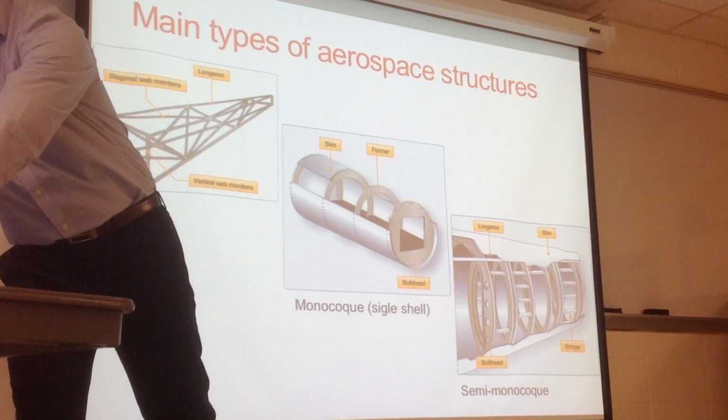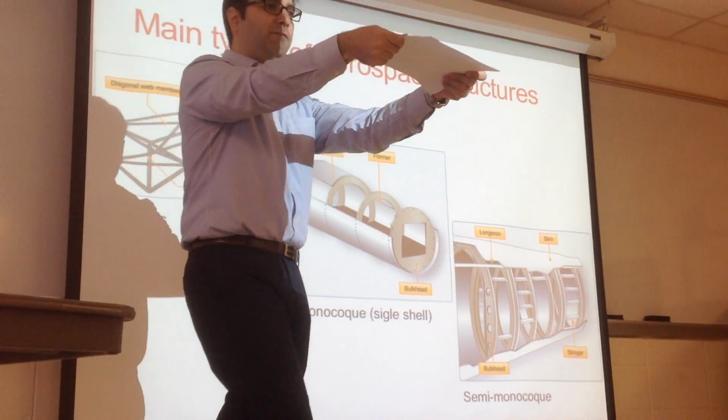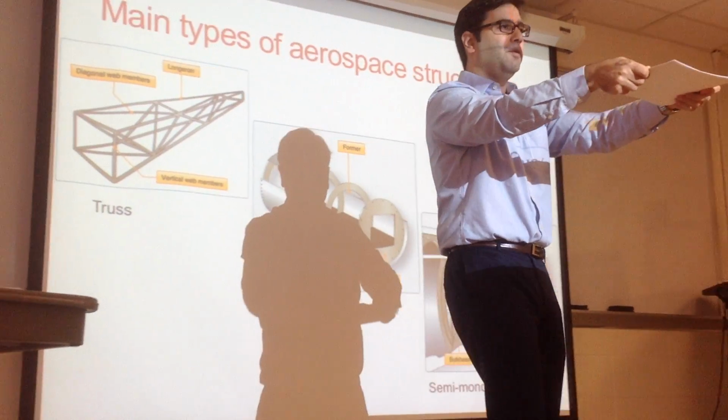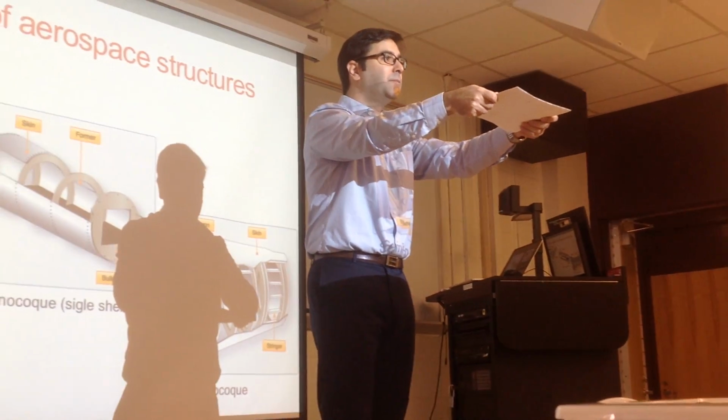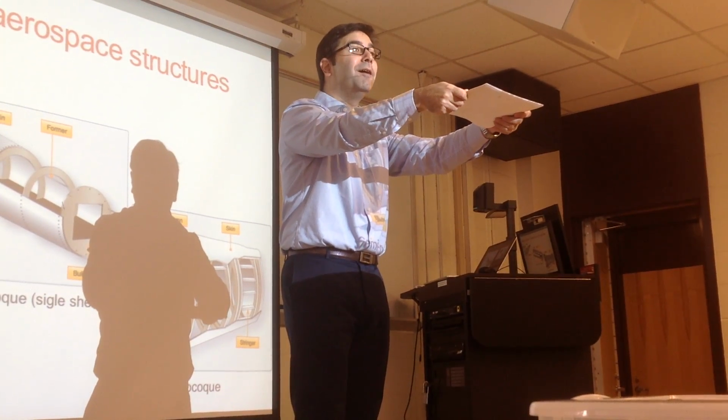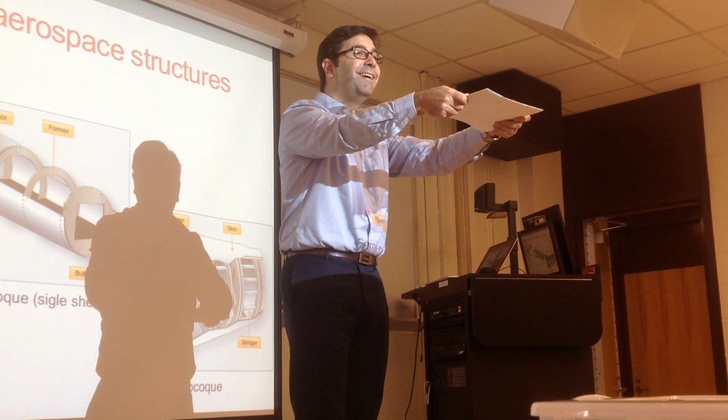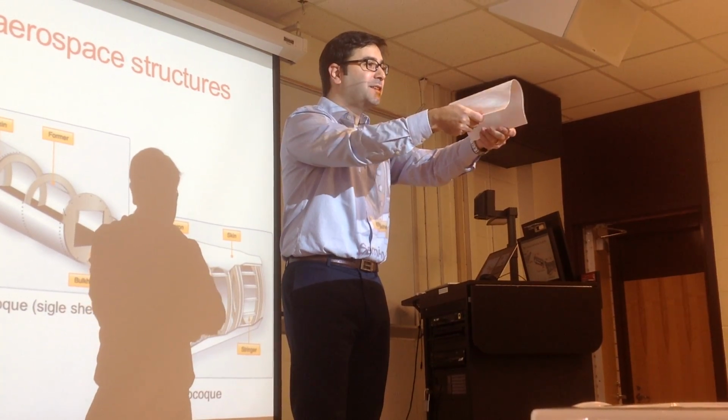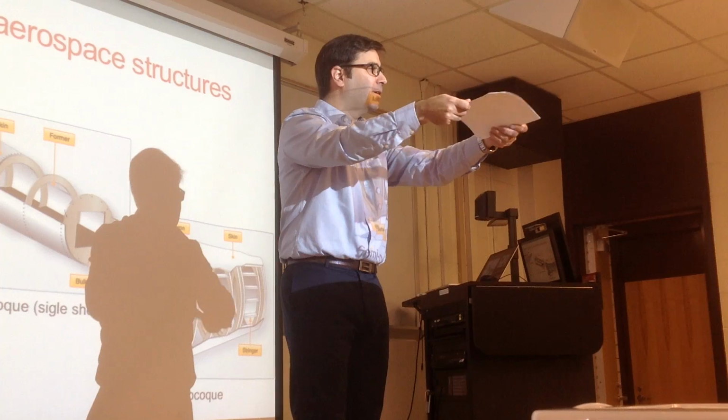The part that is under tension, you just pull it, and it's fine. But the part that is under compression, what happens when you compress this thin sheet? Yeah. What will happen? It comes out, right? It doesn't take any load. This is called buckling. Okay?